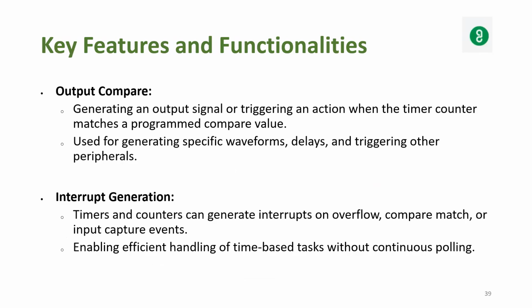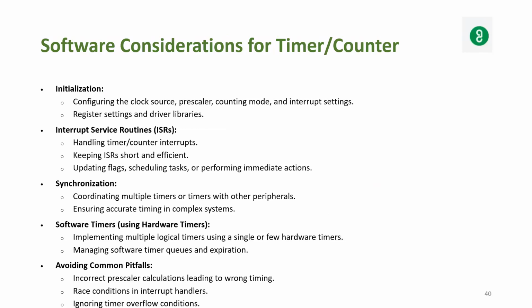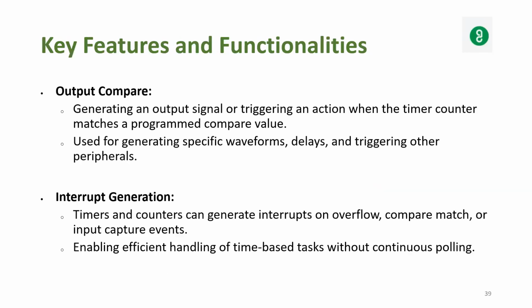In interrupt generation, timers and counters can generate interrupts on overflow, compare match, and input capture events, enabling efficient handling of time-based events without continuous polling. Polling is very time consuming, and continuous polling can be avoided with interrupt generation.